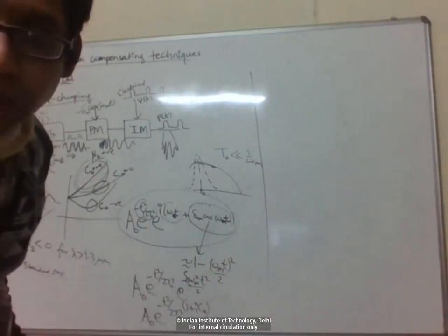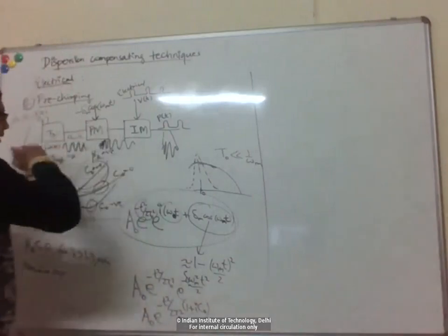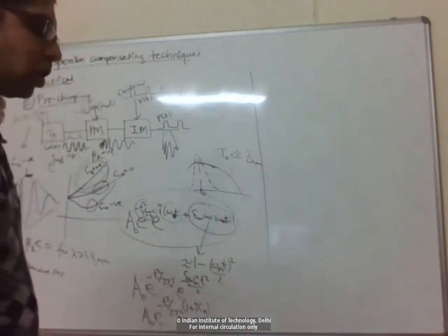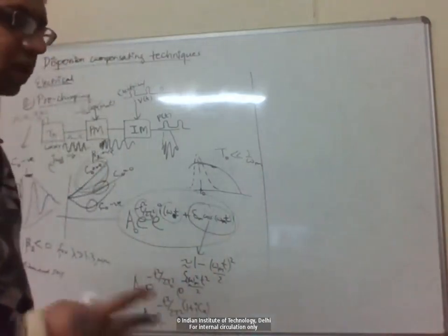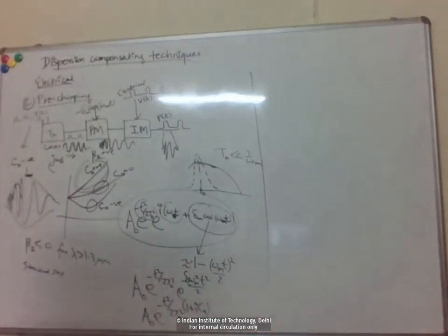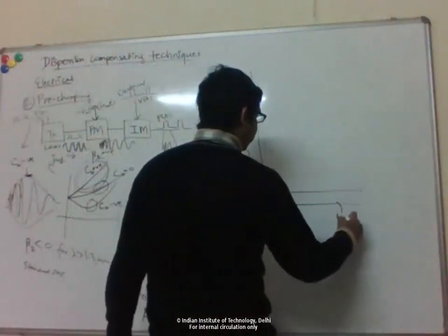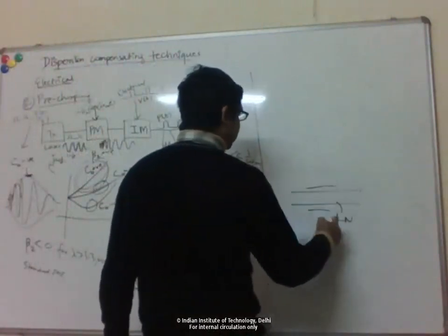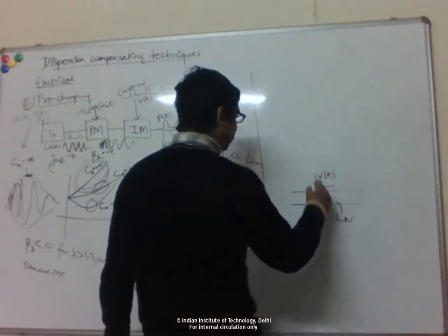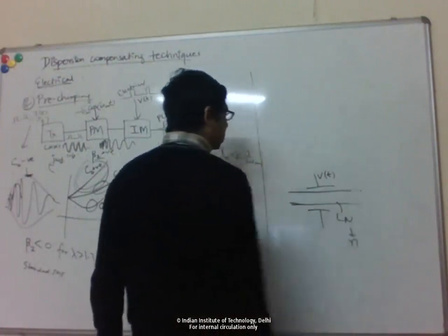And then, what device is used for phase modulation of the laser? These are electro-optic modulators, both intensity and phase, and you can even have more complicated types like IQ modulators, etc., that you use for more advanced modulation techniques. All of them are based on this lithium niobate technology, right? So lithium niobate is a material whose refractive index depends on the voltage that is applied. If you apply some voltage across the material, its refractive index changes.